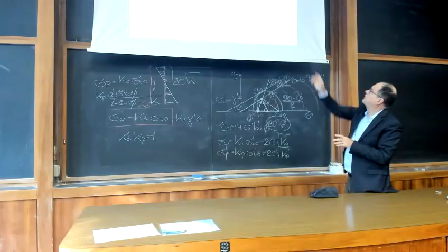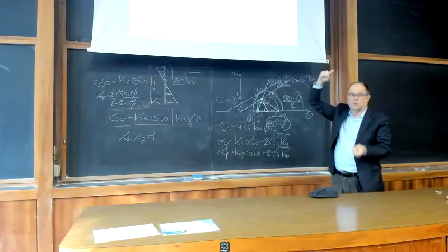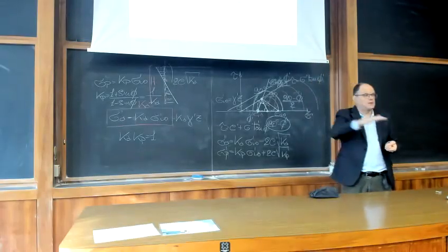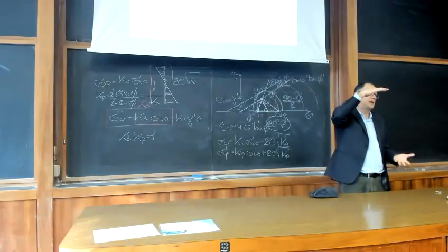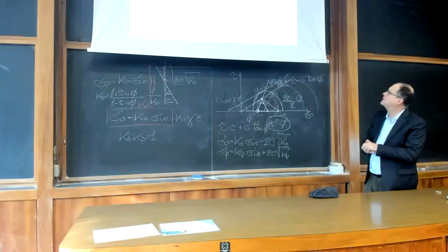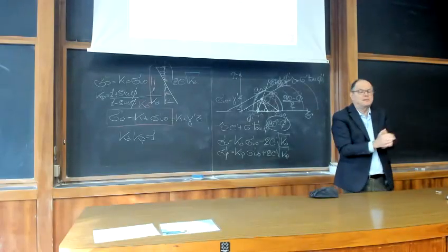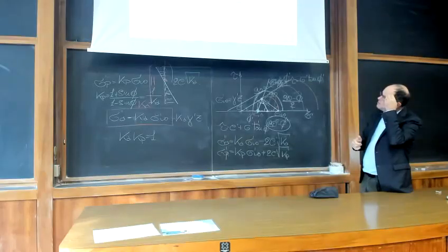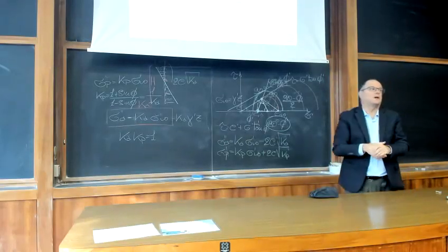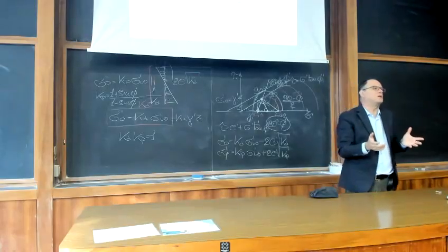So a deep foundation is when Df, which is the distance between the ground surface and the bottom of your foundation, so in this case can also be thought of as the length of the pile, Df divided by B, where B is this time the diameter of your pile, which is the breadth of your footing, is greater than 15. Now, of course, what happens between 2.5 and 15? You have a moderately deep foundation. You have something in between, something intermediate.